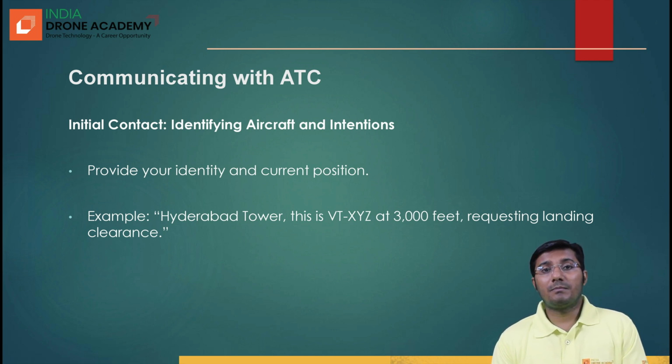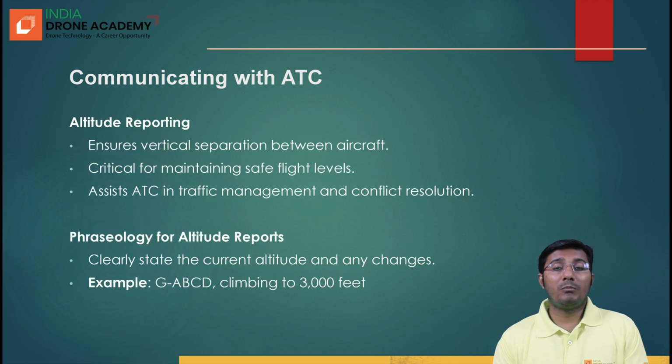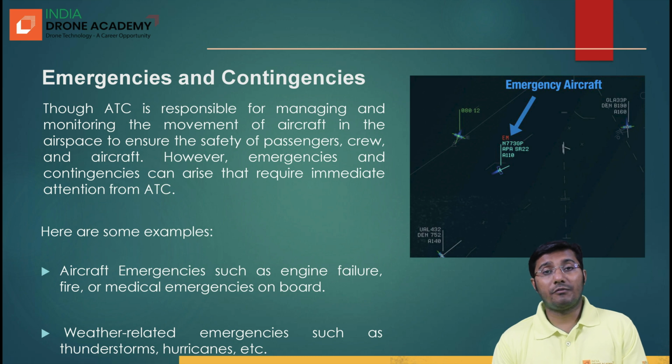In that case, there are some procedures which the pilot has to follow. There is equipment on board an aircraft which is a transponder, and pilots are advised, in the condition of communication failure or in a condition of emergency, like if they got hijacked, to enter a transponder code, which is also known as a squawk code. The transponder is the equipment which can transmit the information related to the code entered by the pilot, and it can be retrieved and understood that this particular aircraft is going through a certain emergency situation.